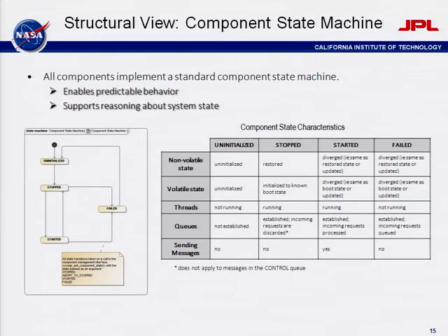The idea here is that in a space and time partitioned system, what you're now capable of doing is transitioning that instrument component to a failed state and then continue to process and continue to run the rest of your system. So by separating your non-critical functions from your critical functions, adding the protection of space and time partitioning, you can actually transition a component to a failed state and continue your mission. So you're increasing system availability.